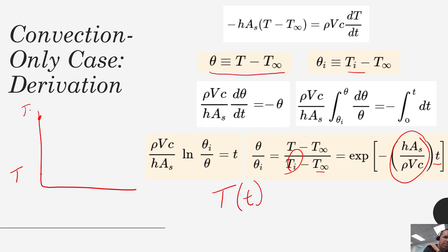And we have our initial temperature here and T infinity up here. So if we're thinking about this in terms of our energy balance, those terms might flip. Convection would be coming in rather than going out. But either way, the math ends up being the same. So we would expect our temperature to asymptotically approach that T infinity, to get exponentially close to it, and eventually level out to be at thermal equilibrium with the surroundings.